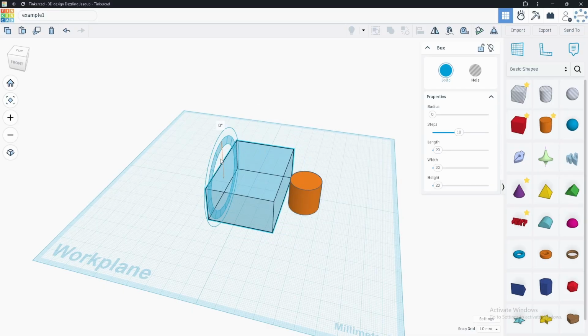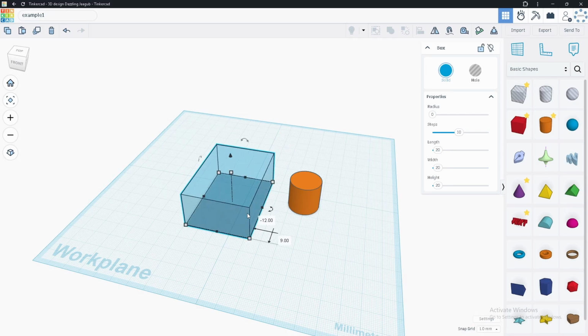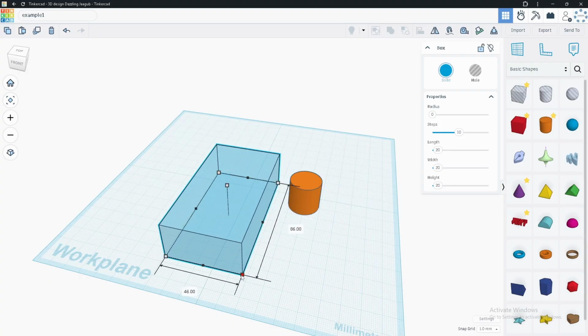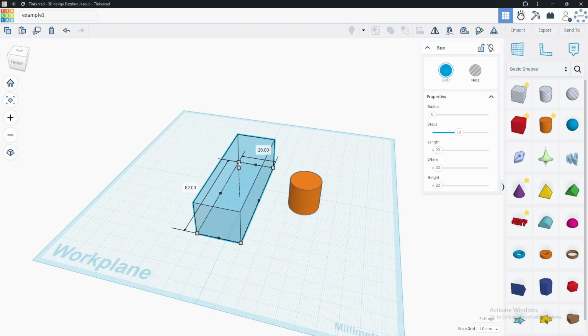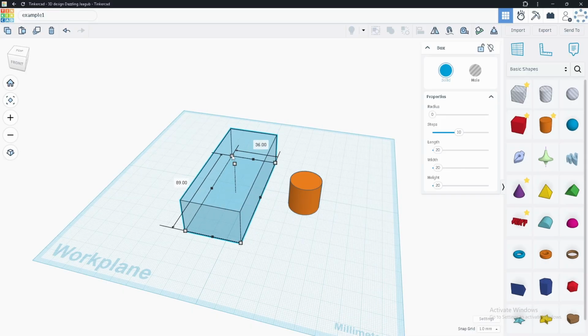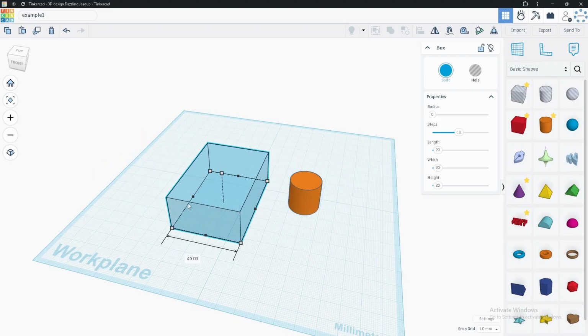All right, now about these particular shapes, you can resize them, you can rotate them in any direction. If you click a white handle, that's these white squares, it will resize it on 2 planes, in 2 dimensions, right? So we can stretch it this way and that way. Now you click these black ones and it resizes it in 1 direction. You can invert and go back upon itself. So white goes 2 ways, black goes 1 way.